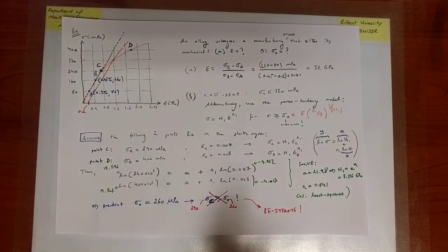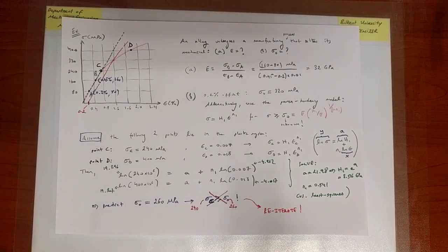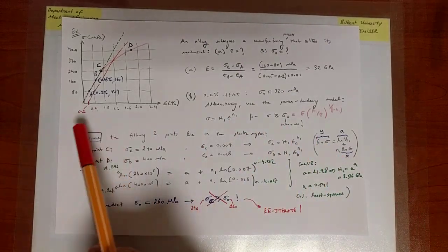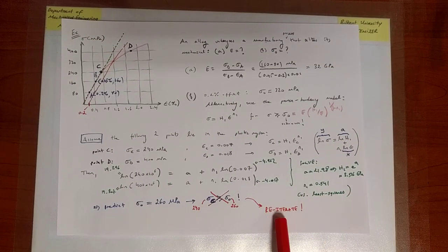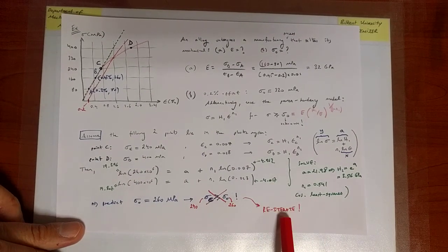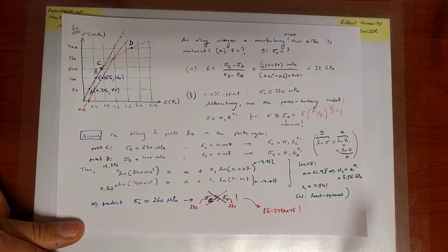So I specifically chose the elastic power hardening model to illustrate this difficulty. Sometimes to determine the model parameters, you have to make assumptions, and at the end of the day, you have to go and check your assumptions. If it's not satisfied, you have to reiterate. If it's satisfied, you're done.